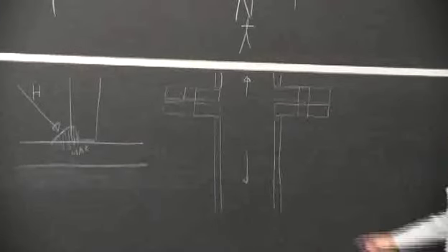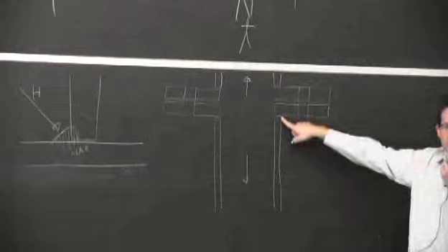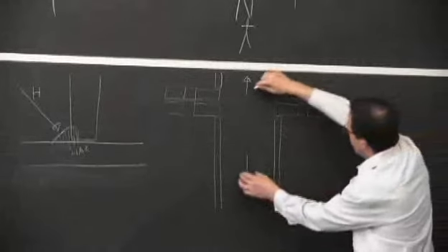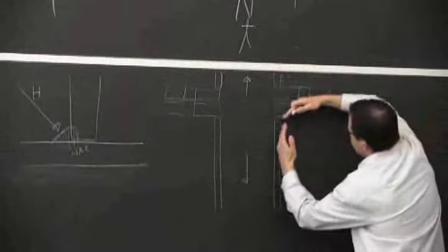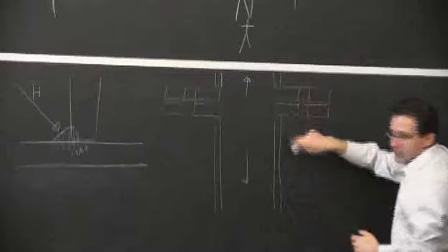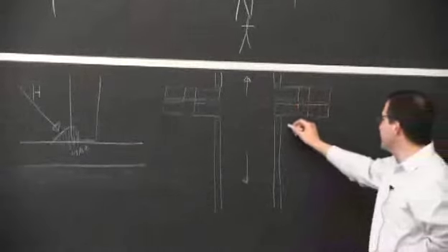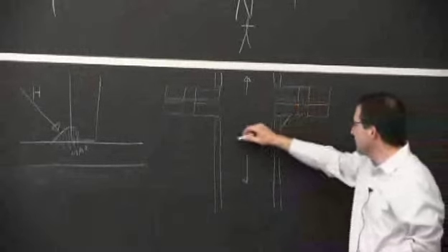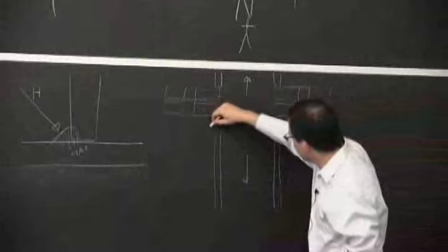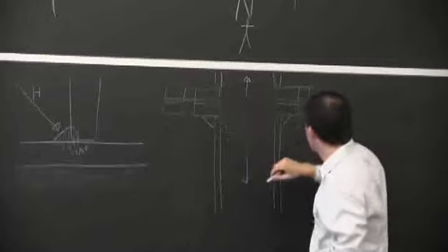And this is the tension spot. If you pull on this assembly, you'll see that it's going to try to open up in this corner. And it's too bad, because that's where our weld is. That's where we want to weld here on each side, because we have access.